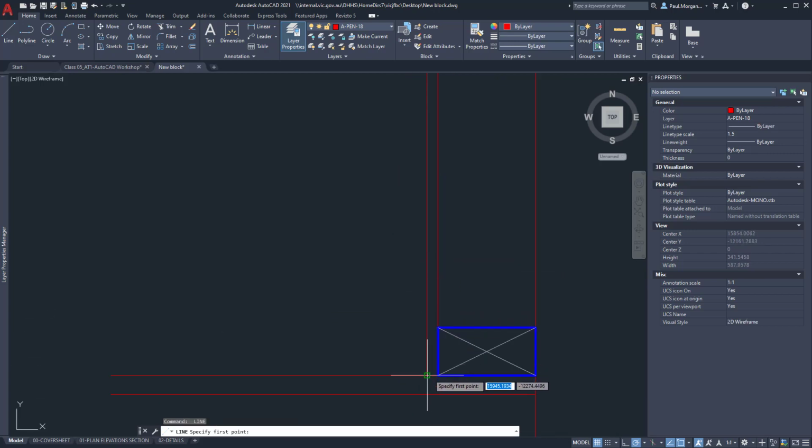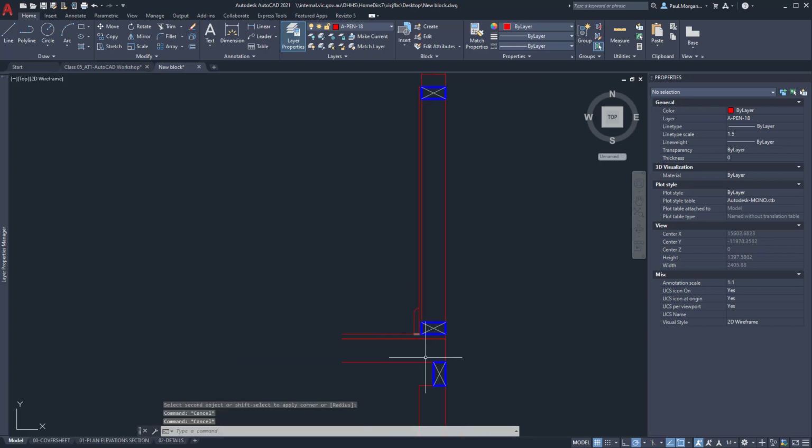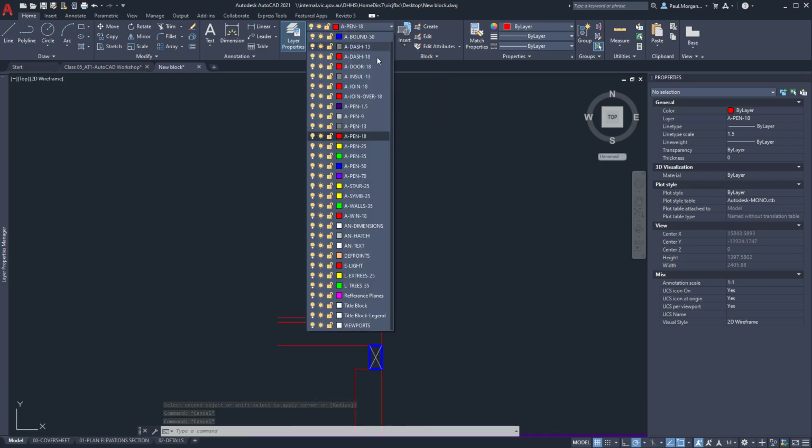I'm going to draw a skirting. So I'll come out, say, 18 mil. Come up, say, 100. Come across 18 and then finish that off. And then I'll just fillet this edge, and I'll fillet it by, say, 18. One smaller. Fillet, 18, something like that. So there's our skirting board. That's quite easy.